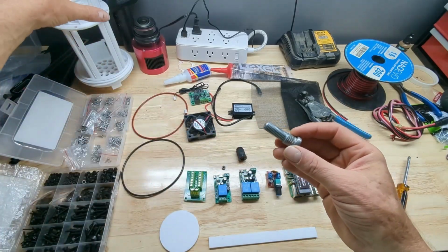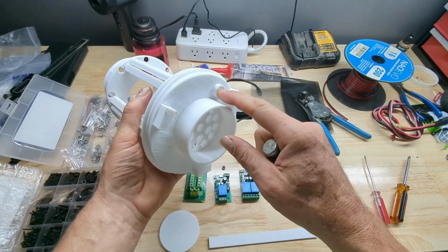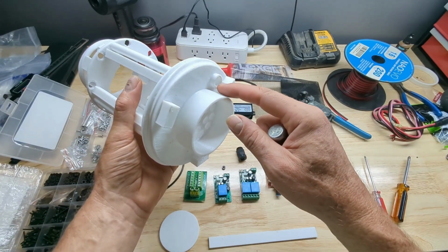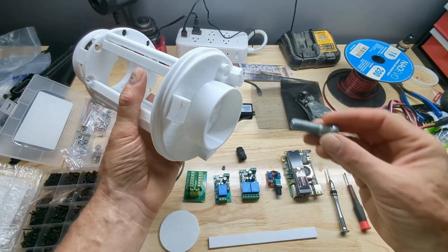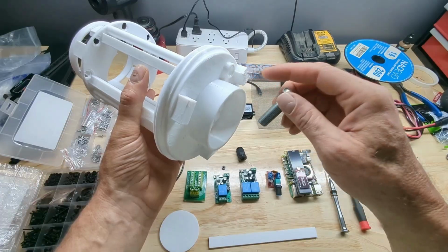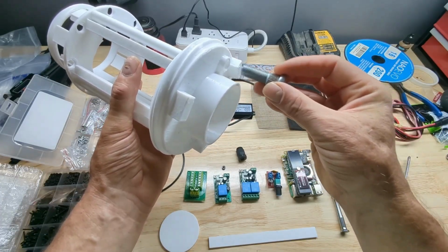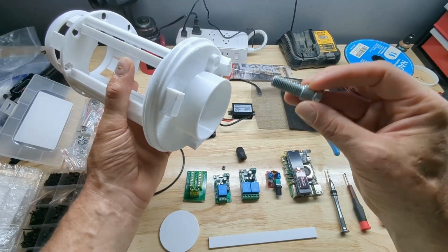And the reason you want one of these is if you do 3D print this yourself, this hole right here, I've printed threads inside here, and it's 12 millimeter threads with a 1.5 millimeter pitch. Some printers aren't very accurate when they're doing this, or they can get some debris inside there. So when you try to put your wire gland in there that you're going to run your power through, it may not thread very well because you're going to be trying to twist plastic into harder plastic.